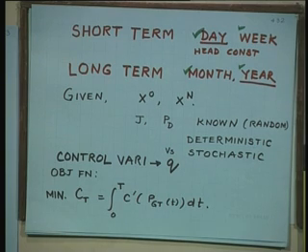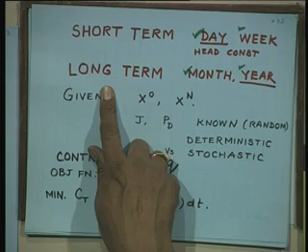Bhakra head will not change drastically today, the 23rd of November. At 5 am, whatever was the head, it is likely to remain same, more or less. It is so huge reservoir. But for a month, head can change. So, head variations must be taken into account if you are solving long term problem.